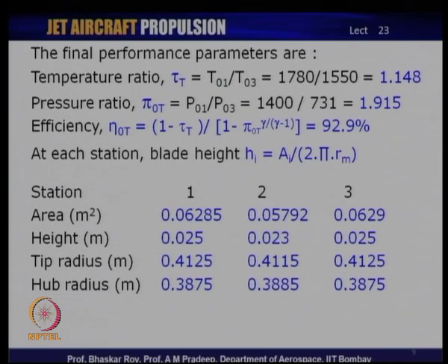So, this table gives us an idea about the changes that typically occur across a stator and the rotor. This may vary from one kind of turbine to another. If you go from HP to LP, these variations would be slightly different. If you go across to the last stage of an LP, it will be again slightly different.